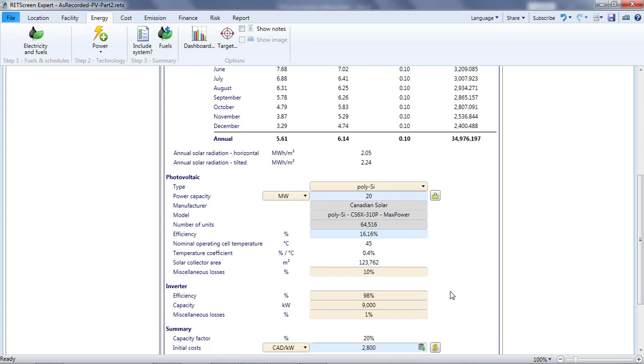For a big project such as this one, the inverter capacity is typically around 20% smaller than that of the array. Yes, for a few hours of the year, the photovoltaic array will generate a bit more power than the inverter can handle. And during those hours, the inverter will waste that small portion above its maximum input rating. But in compensation, the cost of the inverter is reduced by around 20%. I'll assume an inverter capacity of 16 megawatts for this 20 megawatt project.